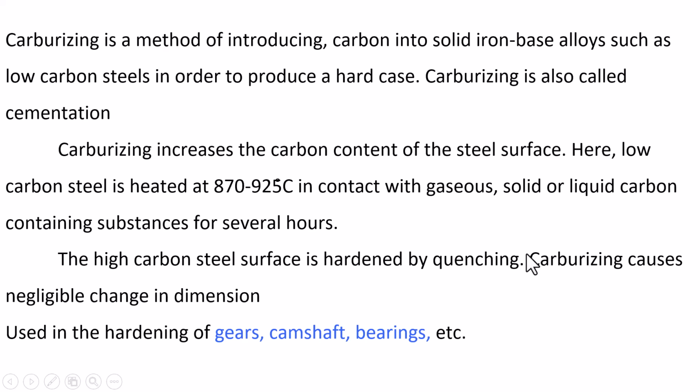The important peculiarity is that carburizing causes negligible change in dimension. If you are heating the material and doing some other process to increase the hardness, dimensional change may occur. But in this case, it is by diffusion, so there is no dimensional change or very, very negligible. For example, carburizing is used in gear manufacturing, for gears, camshafts, and bearings.